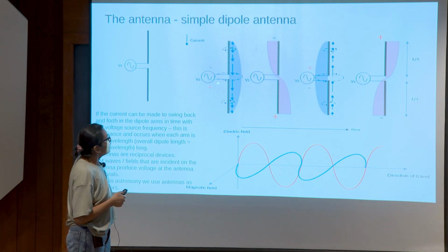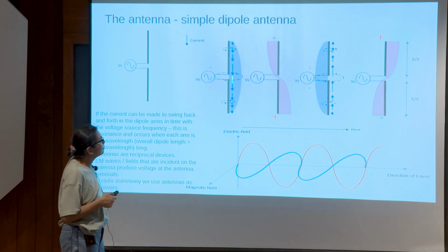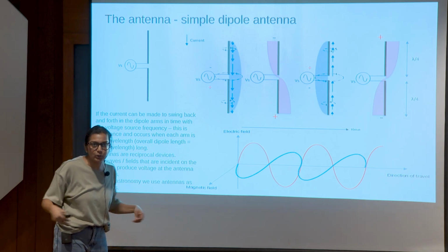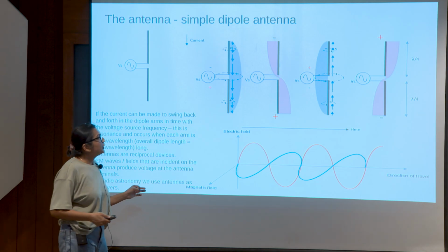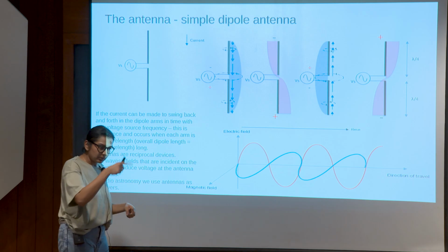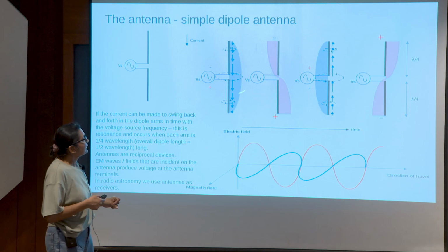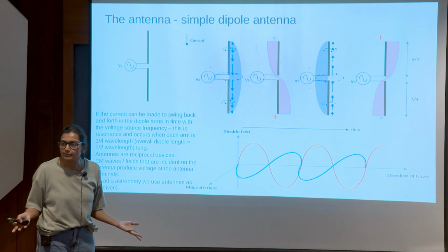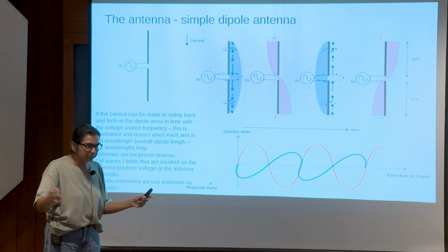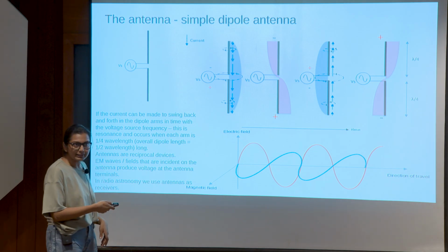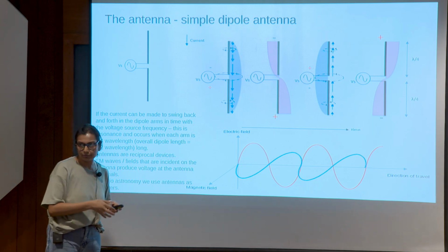Now, when you apply current here, there is current flow, and charges accumulate at the ends, because where will it go, right? It cannot just jump out of the wire, okay. So there is an accumulation of charges and then your electric field will collapse, because your voltage source is changing polarity, okay. And then the magnetic field also collapses because there is no more current, okay. So you have a release of electric and magnetic fields that go out. And of course, this is a transverse electromagnetic wave, TEM, okay. So they are perpendicular to the direction of flow of the wave itself, okay.